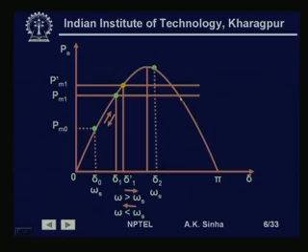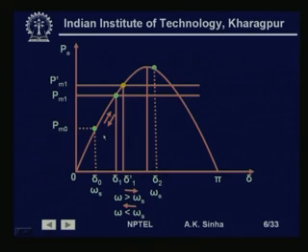So again, the rotor angle stability of the system for large disturbances depends on both the size of the disturbance and the operating point where we are operating. This is one of the reasons why we always operate at a rotor angle much less than the maximum power that can be transmitted through the system.